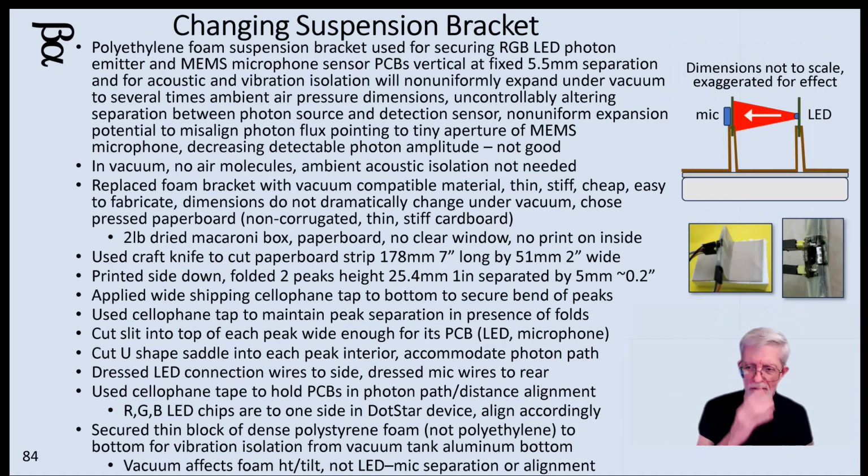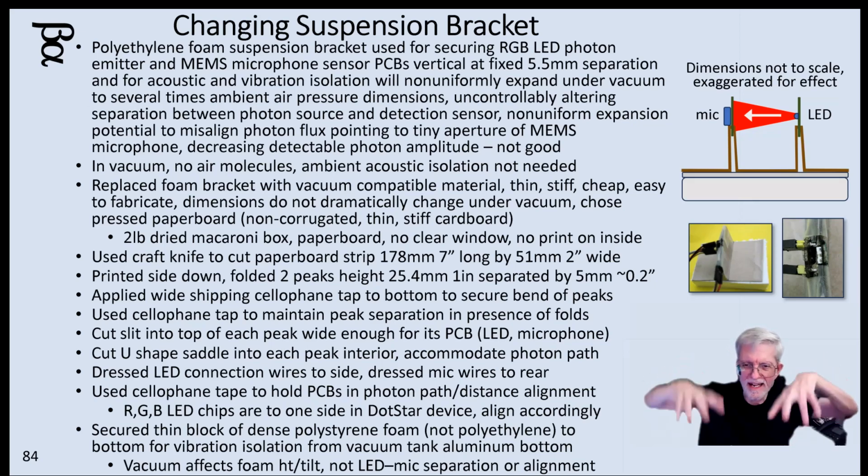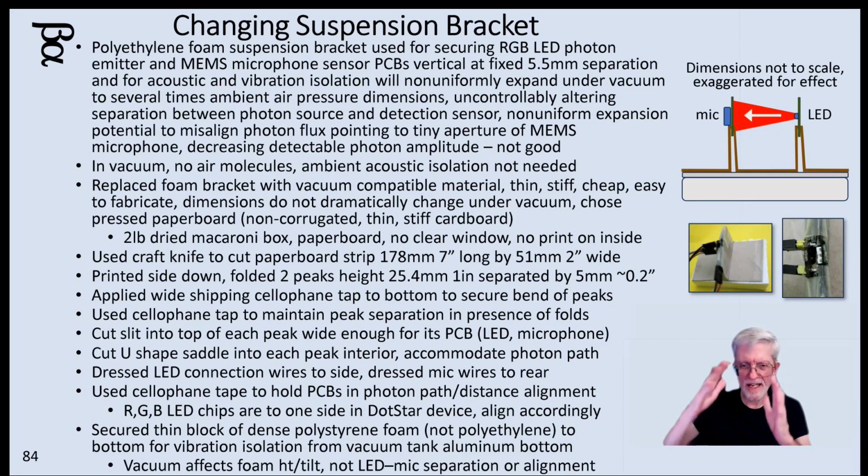If you remember from the earlier video, in order to acoustically and vibrationally isolate my LED photon emitter from my piezoelectric MEMS microphone, I put it on a polyethylene foam block. Great when you're in normal atmosphere. The little air bubbles inside the polyethylene will uncontrollably expand under vacuum. And I didn't want that to change the alignment of the photons hitting the microphone, and I didn't want it to tilt things out of alignment.